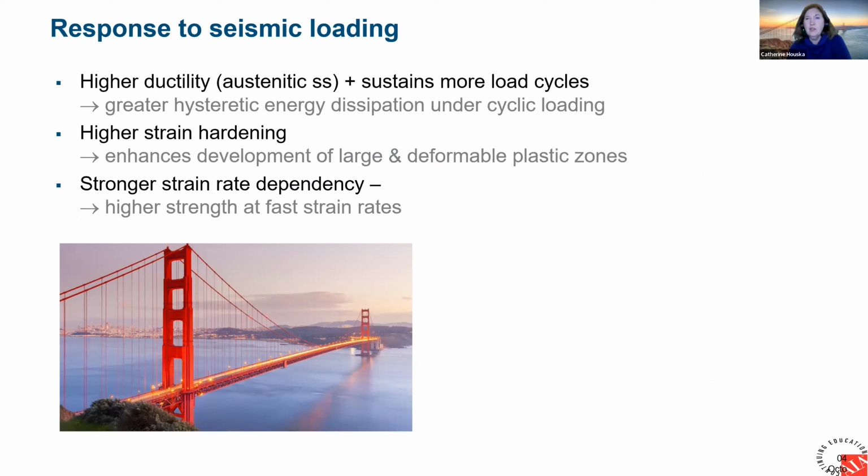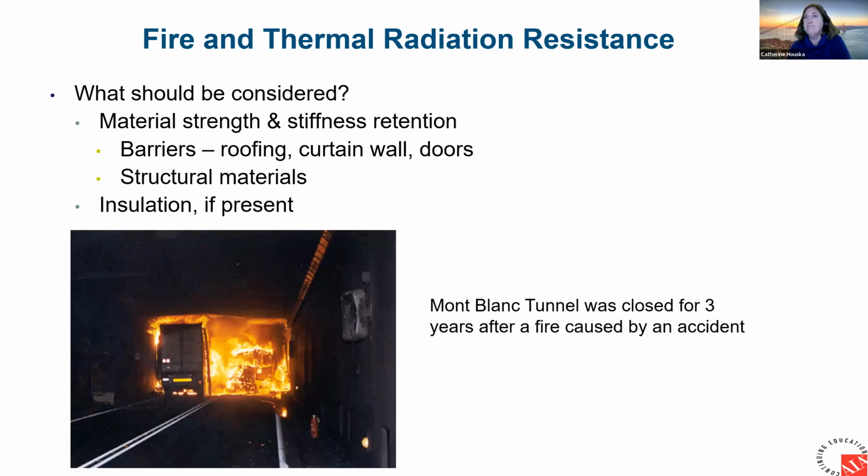We don't include seismic events in 370 right now. There is a good reason why stainless steel is used for seismic applications and why we're working to add it to 370. The Golden Gate Bridge: 2205 is going to be used for seismic retrofits for it, once the funding comes through. It's already been approved. But there are many other applications that show the performance of stainless steel in seismic applications.